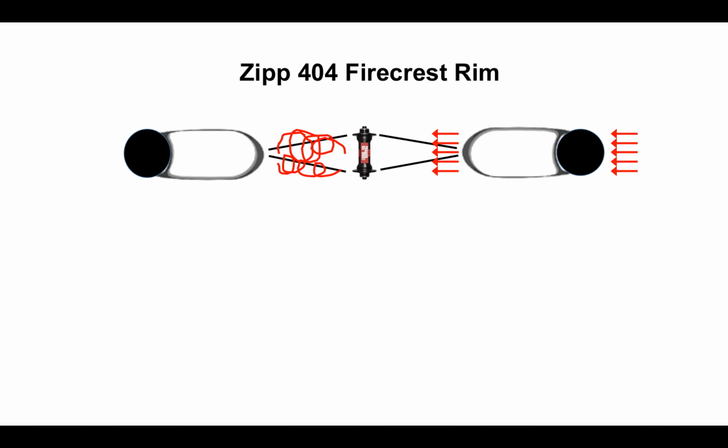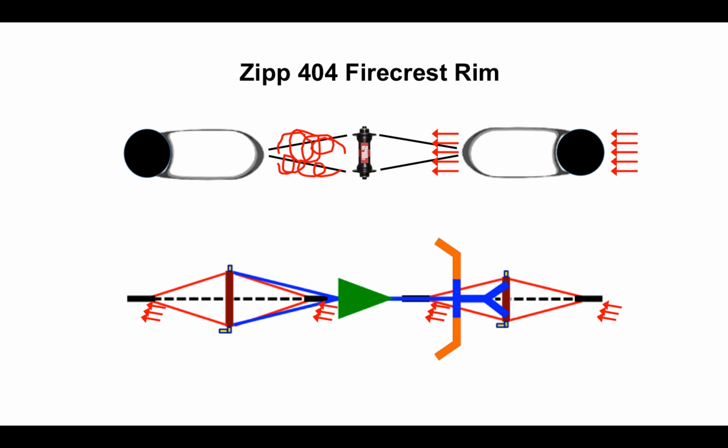This disappointing picture of drag reduction in a front wheel, where you get only a benefit on the front half of the wheel and not on the rear because of turbulence caused by the fork and the spokes, and the same thing happening with the rear wheel, is only going to look like that if the air is coming directly straight from the front, and normally that won't be the case. Normally there's going to be at least some amount of yaw angle, and you have in that case rather pristine air making contact with both sides of both wheels.